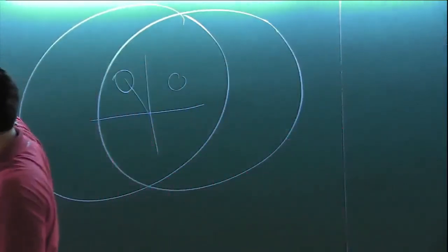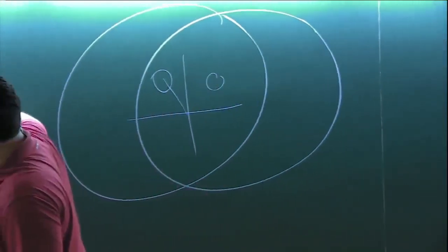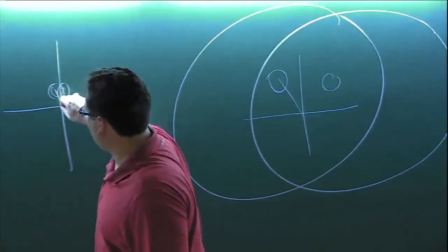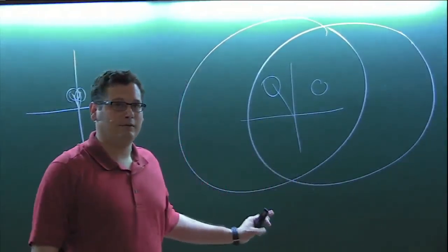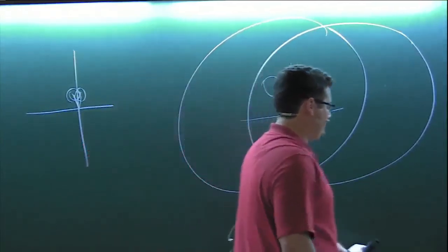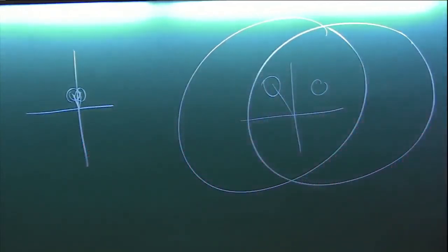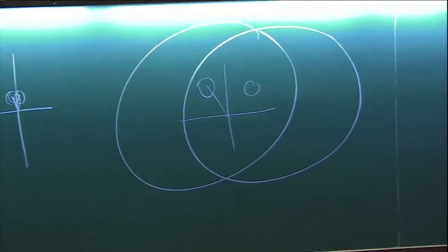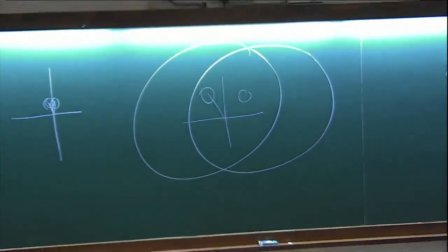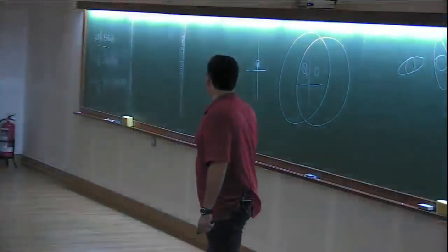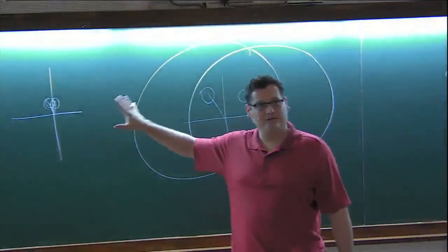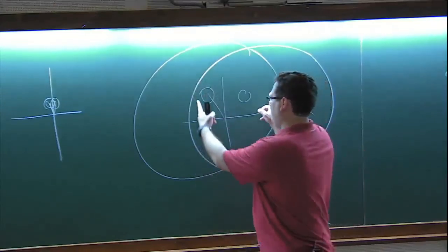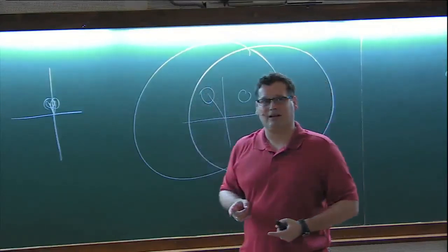That's very different than the scenario where the histograms overlap because I engineered the quantum mechanics to. Maybe one thing that helps this make sense is that I don't usually know the round-trip gain in my system very well. We attenuate by 80 or 90 dB going in. We amplify by like 90 or 100 dB going out. So I don't have a priori knowledge of the voltage that would help me tell the difference between these two. What I usually do is just measure the separation and the sigma and try to extract information from it.